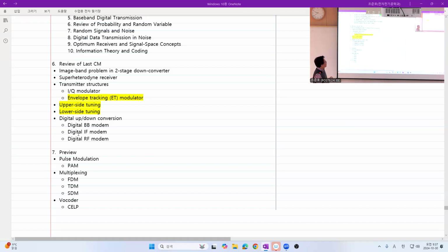And also, not only did he invent the heterodyne idea, he and some others also invented the superheterodyne idea. What is that? In the receiver, we may do something similar. In order to have a simple radio broadcasting receiver which is tunable to your desired radio station, people adopted this superheterodyne idea, where our channel select filter is fixed.